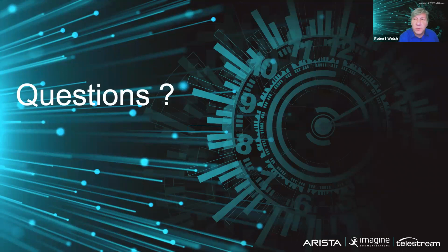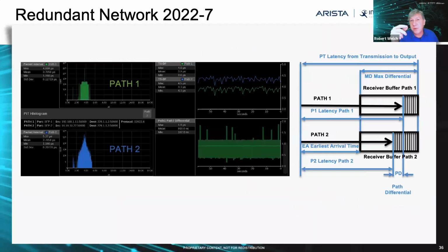Yeah, there's one question that came up here, especially on the -7. If you want to go back to the slide, might be a good example. Prism has two interfaces, and you can see the streams from both, which is great. Can you analyze PTP on both and maybe do some comparison to make sure that things are locked and working properly? So at the moment, the Prism mainly has its PTP on port 1.